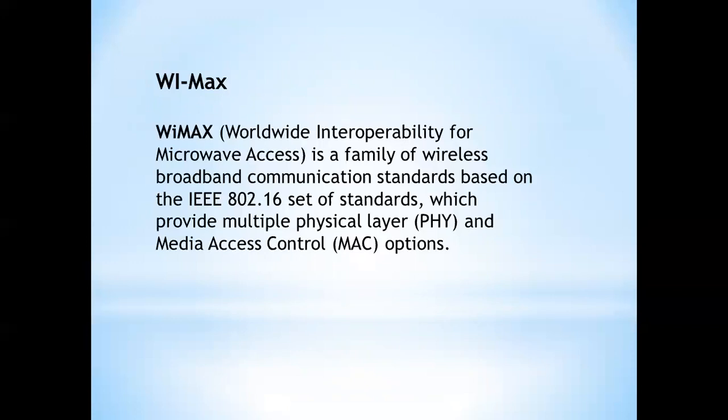There is no uniform global licensed spectrum for WiMAX. However, three licensed spectrum profiles published by the WiMAX Forum are 2.3 GHz, 2.5 GHz, and 3.5 GHz. One of the biggest advantages of WiMAX is the high spectral efficiency. This is due to multiple reuse and smart antenna technology. An inherent problem with WiMAX is that it cannot operate at a higher bitrate over a long distance. We can get higher bit rates or long distance, but not both at a time.